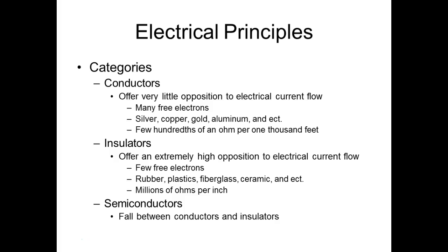Contacts are these switches where we're basically making a circuit by bringing two conductors together. Well, what they normally do is out here on this place where they make that connection, they'll silver plate that. So if you look at a relay contact and it's gray, don't clean it off. That's just silver that's oxidized, or rusty.